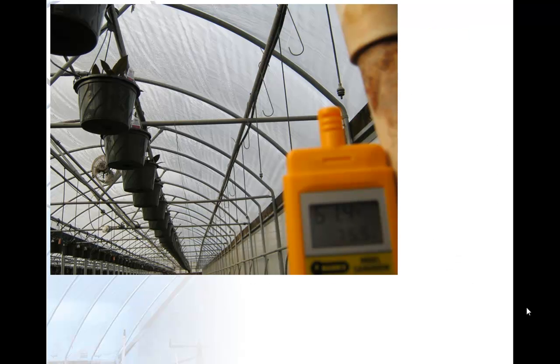In the previous few slides, we talked about different methods of reducing greenhouse humidity. And we have learned that dehumidification is the most energy intensive step of the 4 possible approaches. Thus, the decision for starting a dehumidification process needs to be careful. On an early spring day in Ohio, I went into the greenhouse, looked up, and found the roof is full of condensate. This may be an indication for growers to start a dehumidification process.